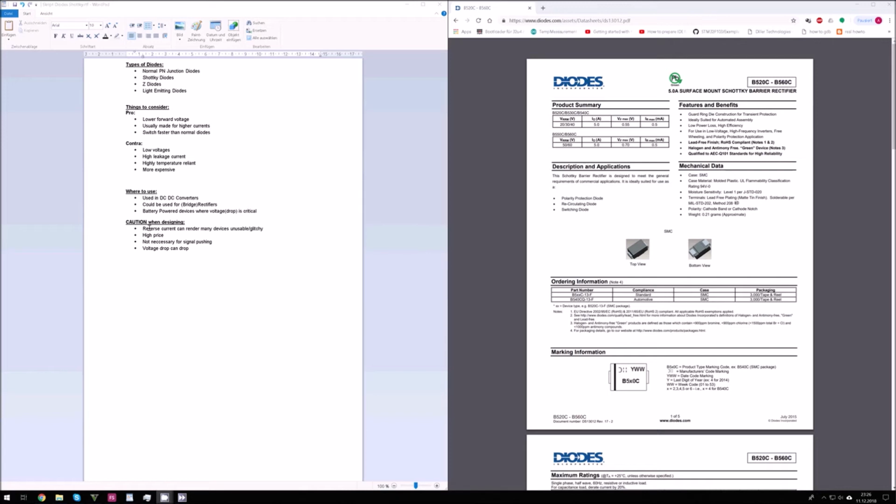So if you have Schottky diodes in your design and something is not working right, you probably have to blame them first. Also, take into account the high price. Not all management decisions will be okay with paying €1 extra for your device just because Schottky diodes could increase the efficiency. But you will have to calculate it out and find out if there's another way to do it.